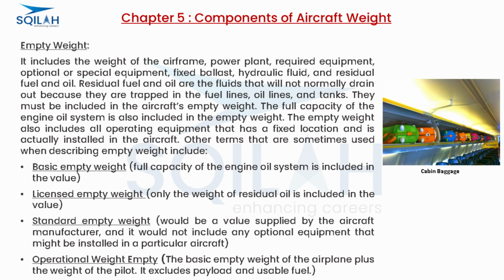Full capacity of the engine oil system is included in the value. Licensed empty weight. Only the weight of residual oil is included in the value. Standard empty weight would be a value supplied by the aircraft manufacturer, and it would not include any optional equipment that might be installed in a particular aircraft.